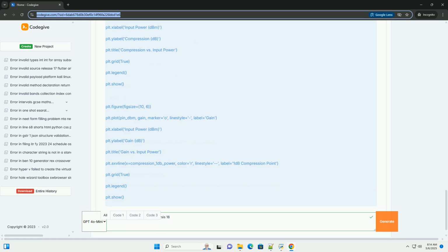4. Measurement errors. Double check ports: ensure that you're measuring the power at the correct output port. Reference impedance: verify that the impedance used to calculate power is correct, typically 50 ohms. Signal selection: if analyzing IMD or harmonics, make sure you're selecting the correct frequency component, for example the 2F1-F2 component for IM3.